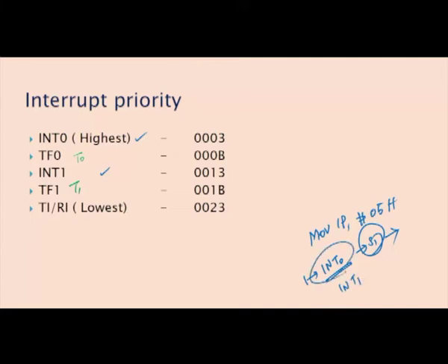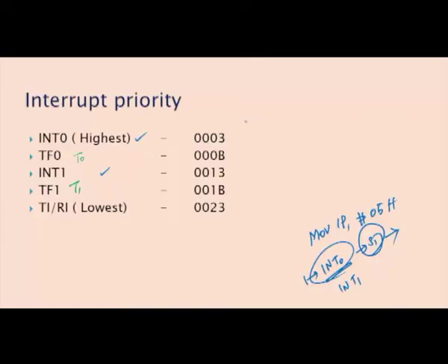So during the service what it will do means, each has a vector address. Vector address means once it identifies the request, the processor or the controller suspends its current work, then switches over to the specified address, which is the starting address of the interrupt subroutine. So it has to switch over. Where to switch over means it has to know the address. Now its vector address is 0003H. So this is the starting address of the subprogram, or you can say it is the interrupt service routine address. Okay. So now it has some set of instructions ending with interrupt return.